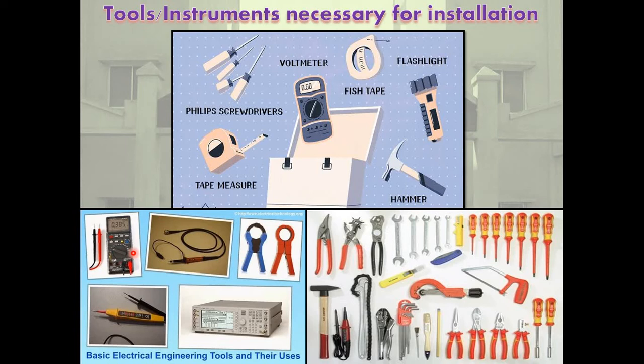Always use insulated tools while working. Always use appropriate insulated rubber gloves and goggles while working on a branch circuit or any other electrical circuits. Never try repairing energized equipment. Always check that it is de-energized first by using the tester.